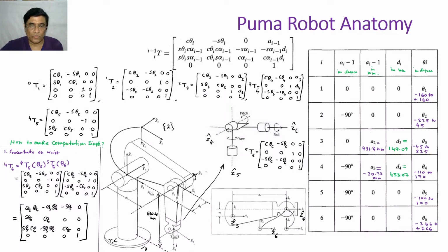Now, once the Z axes are fixed, you need to figure out where the common normal direction is. So here is one Z axis, another, Z0, Z1. So this is the DH table you need to form, and all the parameters are known, in degrees and millimeters. Now the drawing is there. You see, this is A2.